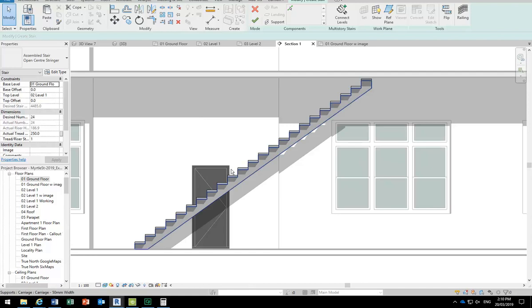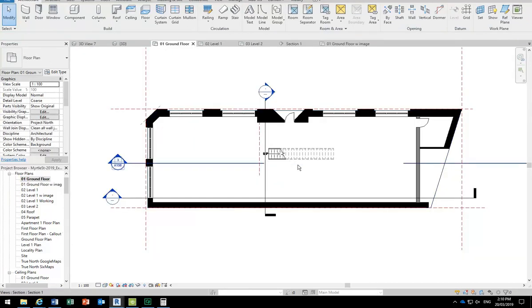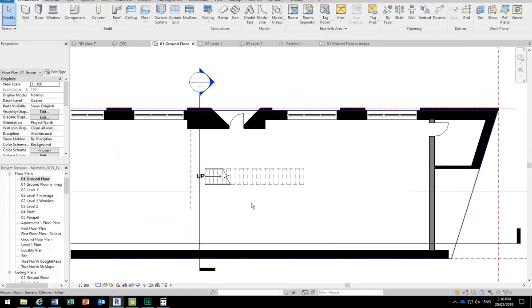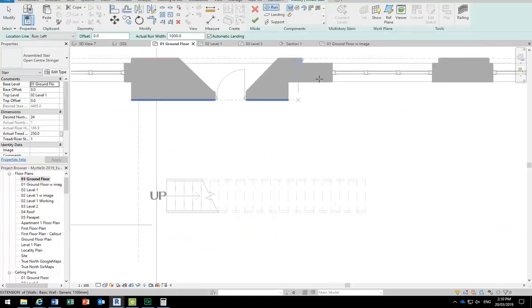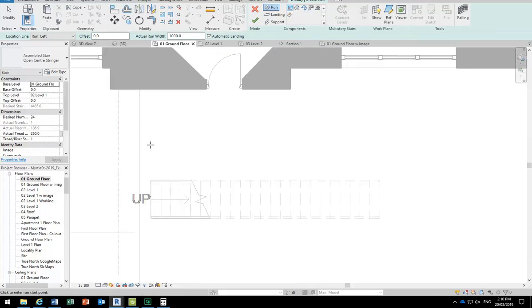So I'll finish this stair and just leave it there. Revit doesn't check to count your risers. You have to do that yourself. So I'll go and make a new stair next to it. And all I'm going to do differently, leaving it on the straight option, is click the start point similar to what I did before, and then come across and count.